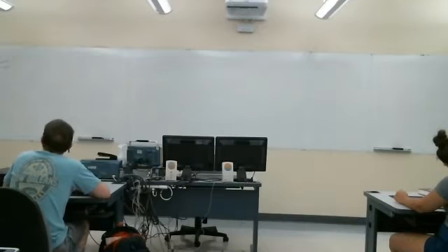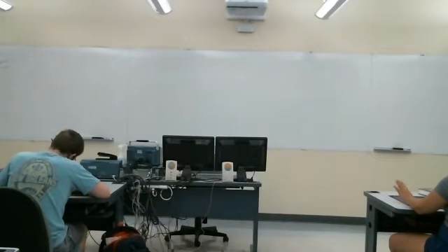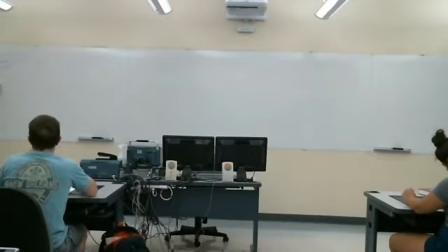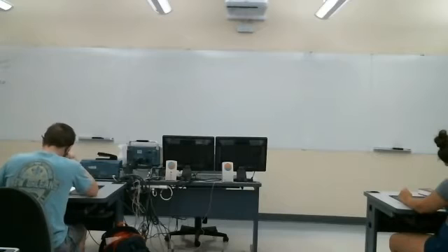It's called convolution. The trick is somehow we have to get the impulse response, and that's not an easy thing to do. If you can get the step response, we can take the derivative of the step response to get the impulse response. But once you have h of t, we can calculate the output by carrying out this integration, h of t minus tau d tau. This operation is called convolution.